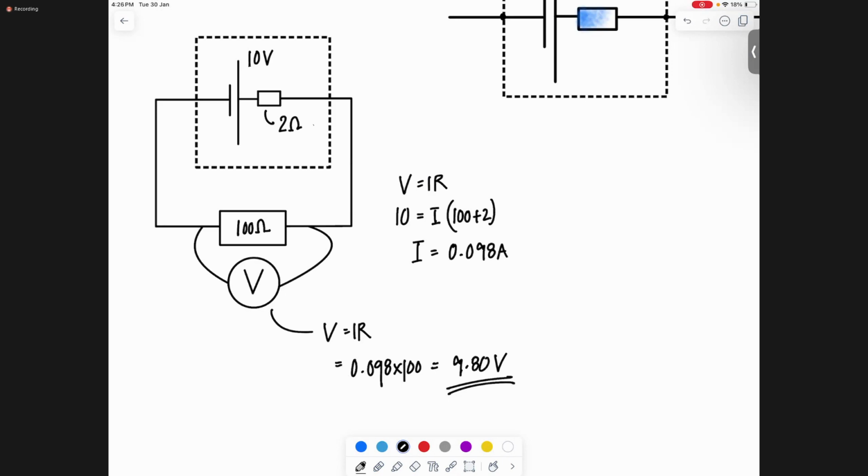Where did the voltage get lost? Man, 0.02 volts হারাই গেল না? 10 এর থেকে 9.98 is 0.02 difference, right? Where did it get lost? Yeah, it got lost inside the internal resistance here. যে এখানে যে রেজিস্টারটা আছে, এই রেজিস্টারটা কি করছে ভোল্টেজটাকে কনজিউম করে ফেলছে।